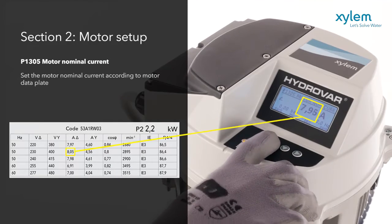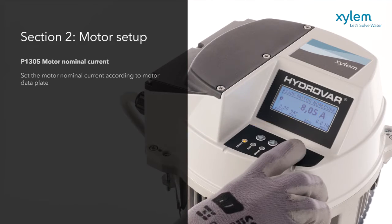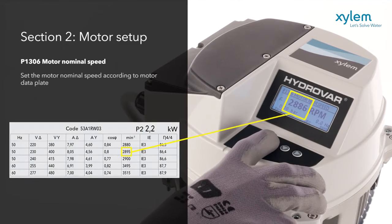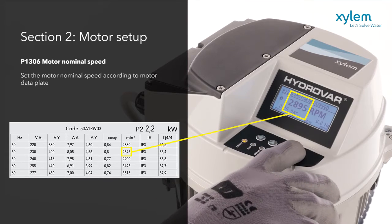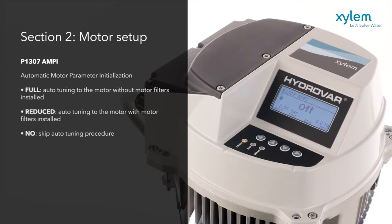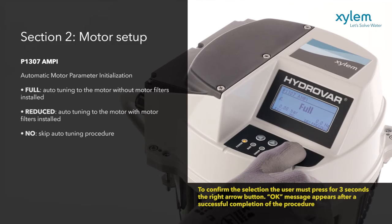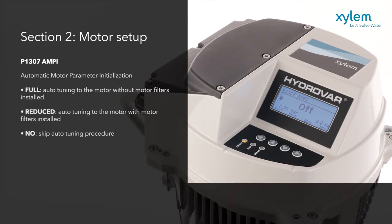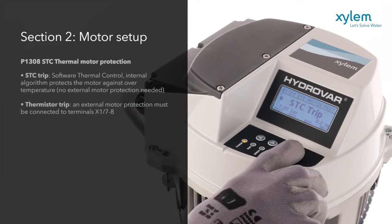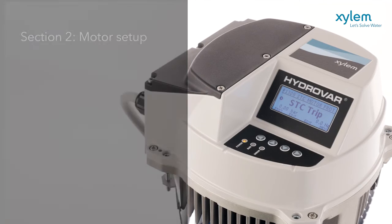If a generic motor is selected, the nominal current and nominal speed of the motor have to be set. Note that the Automatic Motor Parameter Identification process, AMPI, can take up to 3 minutes, during which time no other actions are possible. It's necessary to select the thermal protection settings for your motor, which will protect the unit from overheating. With the STC, Software Thermal Control, no motor PTCs are required as standard.